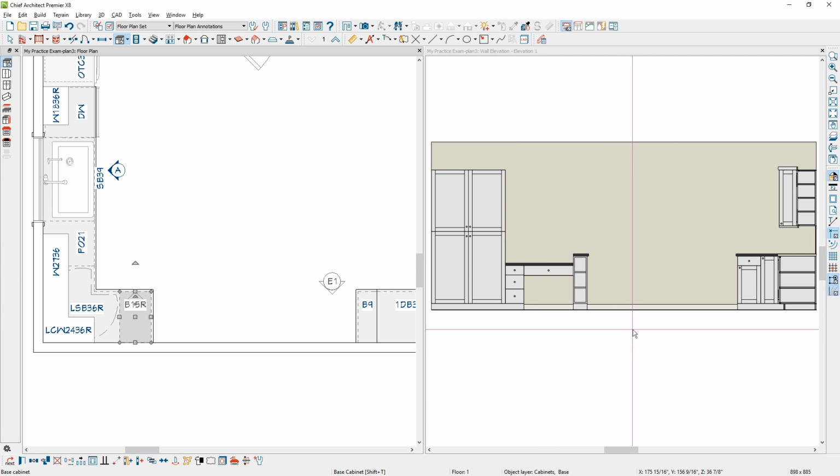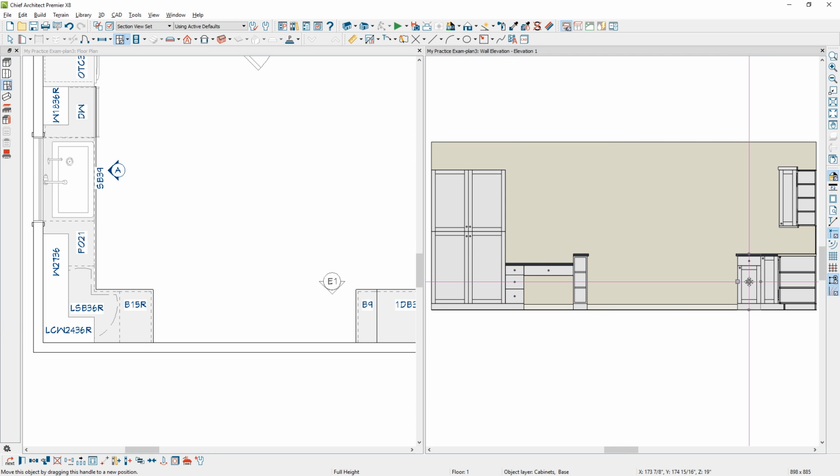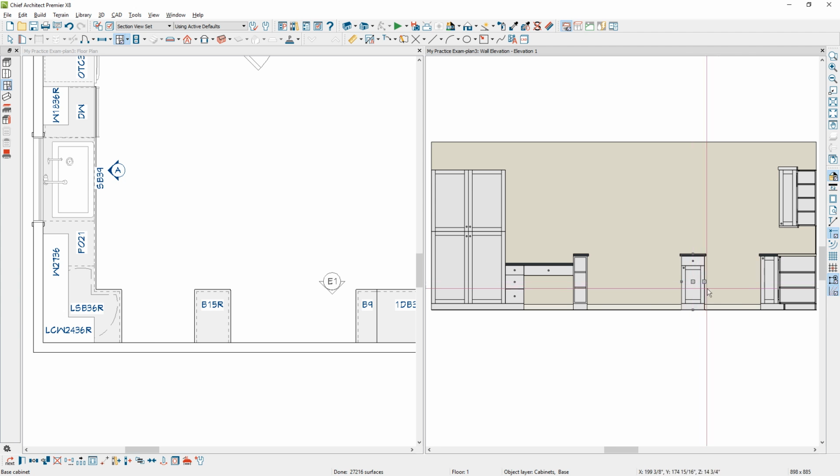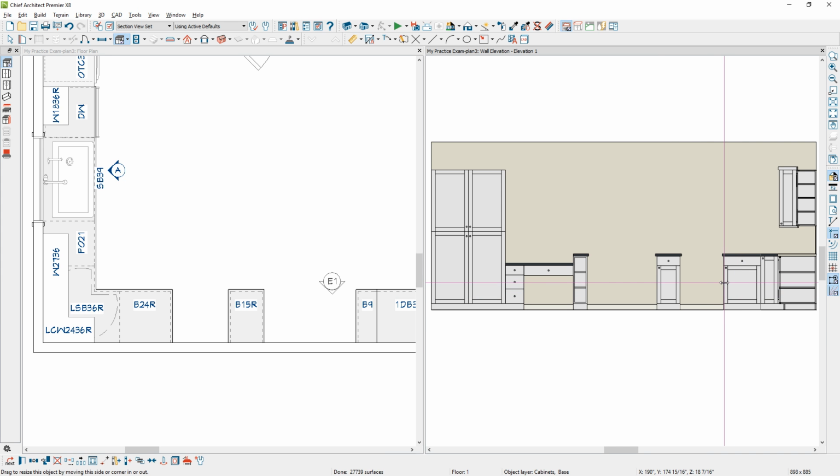And then rather than having my cook range and my refrigerator right together, I'm going to put another cabinet in here for the cook range. Using the base cabinet tool, I'm going to click and place a 36-inch cabinet. Let's slide that over, make sure I have enough room. And I'm going to broaden this to be a 36-inch cabinet. Notice when it gets over 24 or 27 inches, it becomes an automatic double door. That's the face item type called auto door.